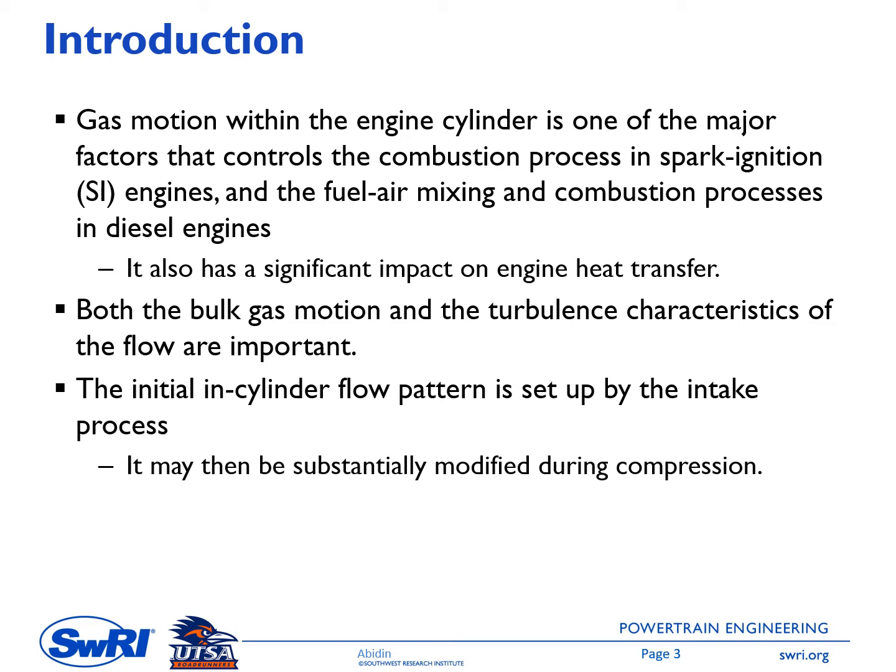So the idea is to have the bulk flow, sometimes called the organized flow if it is in an organized direction, and then break this organized flow into turbulence at the end of the compression stroke. The initial in-cylinder flow pattern is set up by the intake process. Depending on the design of the intake system along with the intake port, we will have a different flow pattern inside the cylinder, and it may then be substantially modified during the compression.